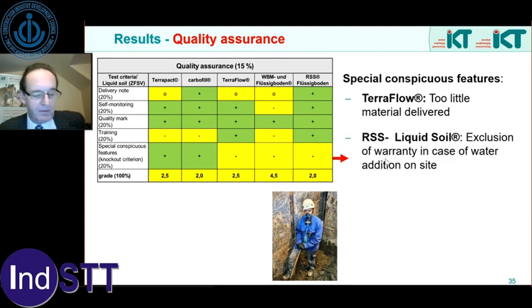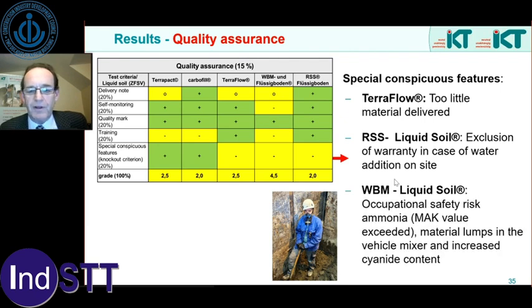One product as well, they ended up adding some water when they got on site in order to make it flow better, and then we discovered that the warranty was invalidated because water had been added on site. And one product, we had an issue when excavating it of the smell of ammonia, which exceeded the acceptable limits, and we ended up having to use gas masks for the staff when they were excavating.